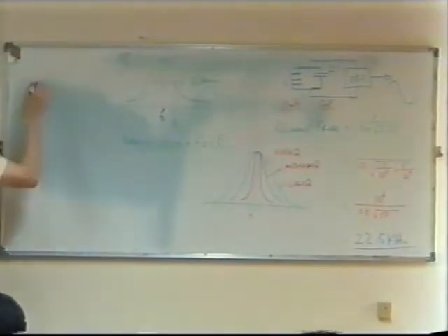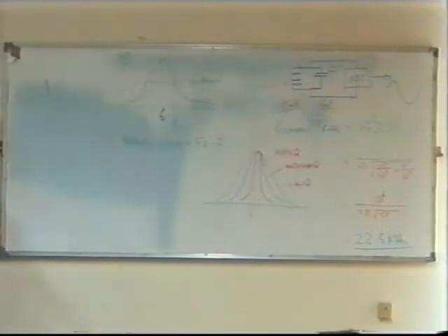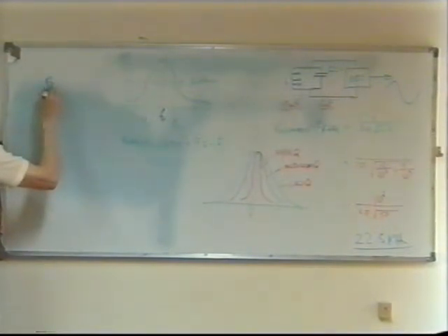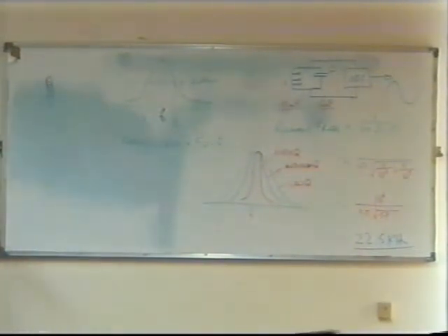they might make an inductor as a coil of wire on a plastic form, a small thing about so big, right? A little plastic tube, and around the tube they'll wrap some turns of wire. That will be the inductance, just a few turns of wire, that's all. You can tell by that it's going to be quite a small value of inductance, isn't it? But what happens when you have an oscillating or alternating current flow through an inductor? It produces a magnetic field, doesn't it?